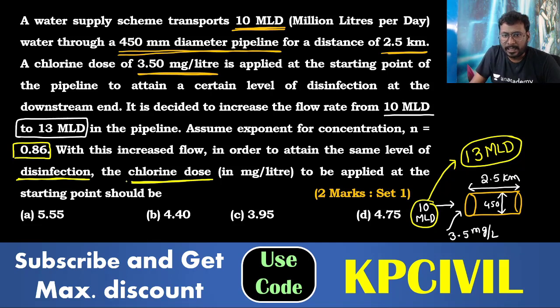So the question is given very clearly. Increasing flow rate from 10 MLD to 13 MLD. Was any information provided that the pipe diameter increases? No, the pipe diameter increase has not happened. Same diameter of pipe, instead of 10 you are sending water of 13. So the area is constant, discharge increases. Velocity of flow increases. Because of the increase of velocity, what decreases? Time of contact. So time of contact decreases.